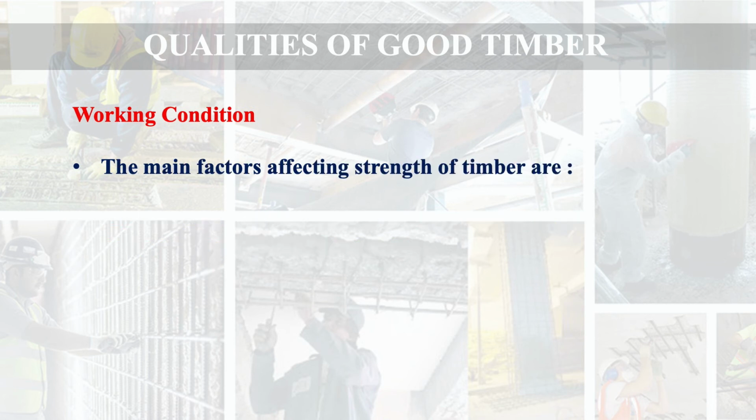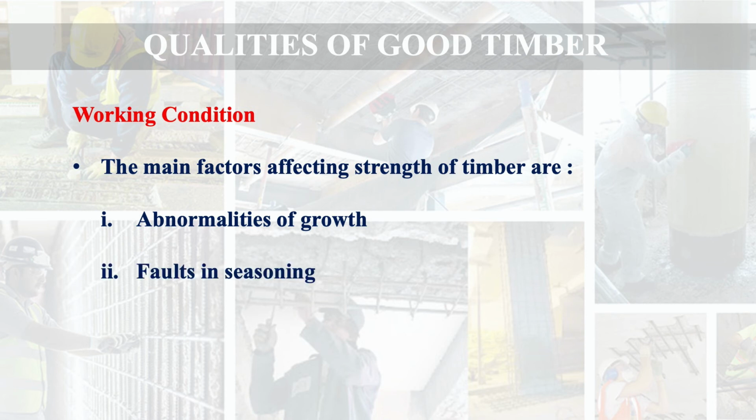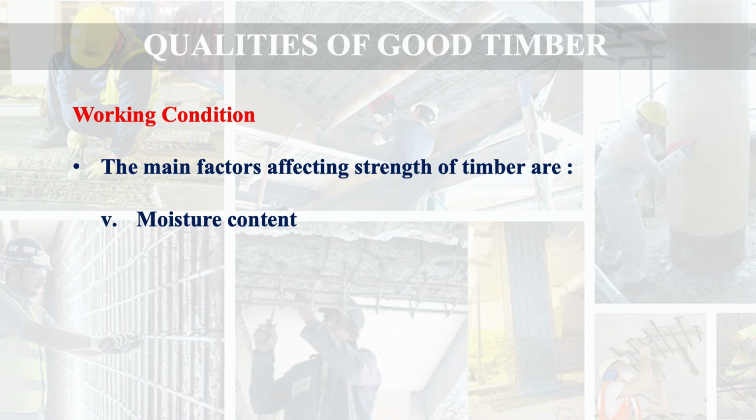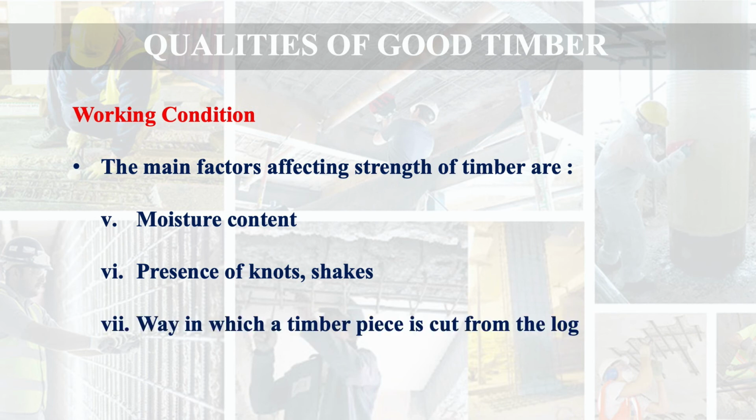The main factors affecting the strength of timber are abnormalities of growth, faults in seasoning, invasion of insects, irregularities of grain, then moisture content, then presence of knots, shakes, etc. And finally, the way in which a timber piece is cut from the log.